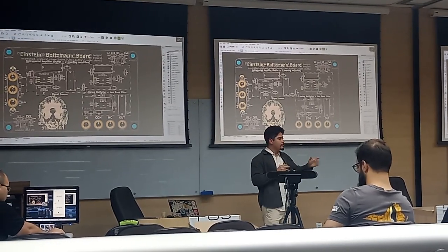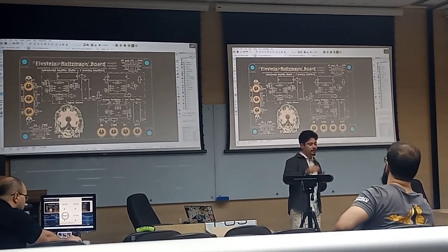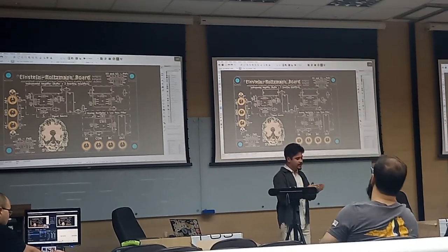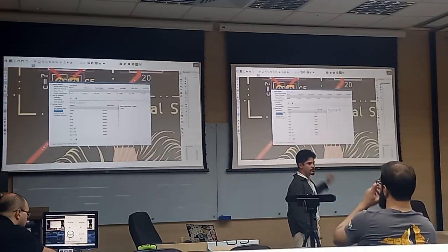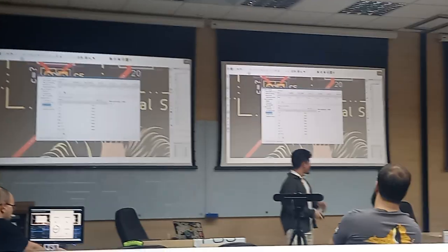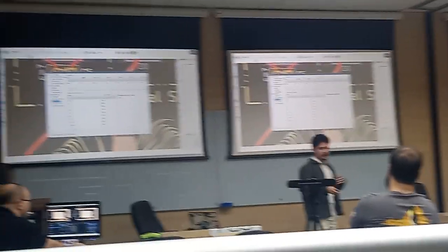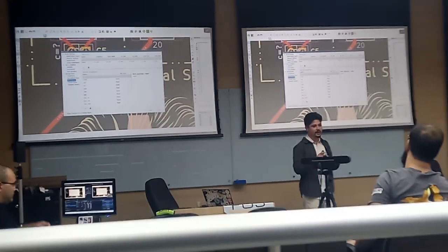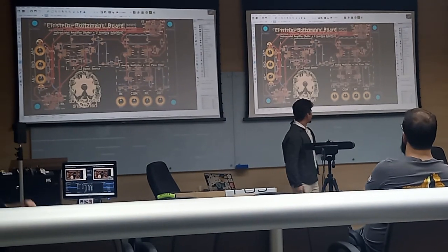And for example, if you want, oh, I want my power tracks much wider than the signal ones, I have a special connection, I want to make it in specific widths. How can you do this? KiCad can make classes. You can specify, I want the power classes to be much wider than the standard ones. You can change this, and with this set, you can just route normally, and KiCad will do the work of choosing the correct width for the tracks. Very powerful. And just make the tracks.